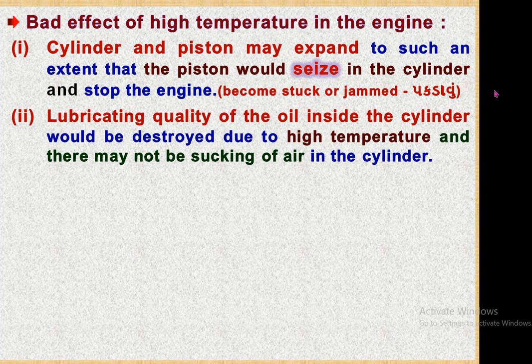Means we know that due to the high temperature, the lubricant oil which has been used to lubricate different parts of the engine may lose its viscosity, may lose its lubricating characteristic. So due to which there may not be sufficient lubricating property in between the piston and cylinder system, and due to which the cylinder may not suck the air, because there may be air leakage in between cylinder and piston due to the loose or destroyed quality of the lubricant oil.